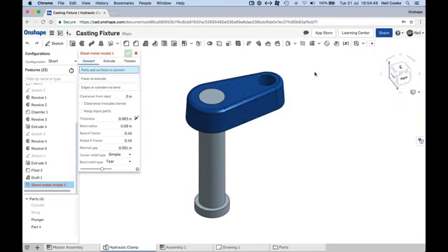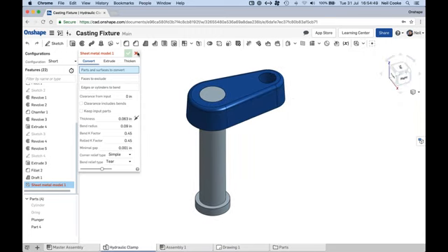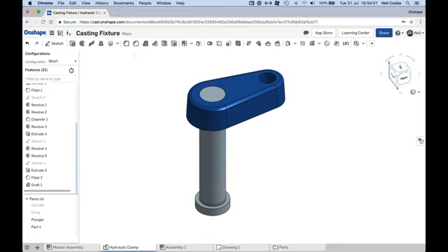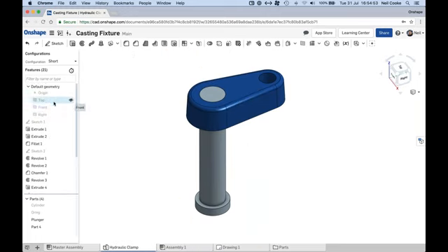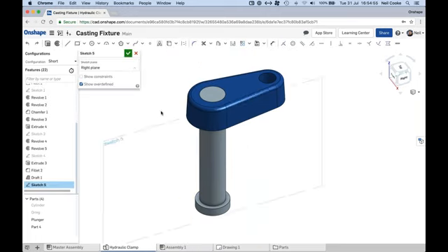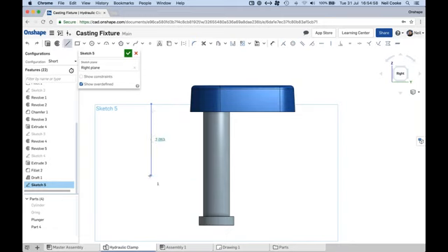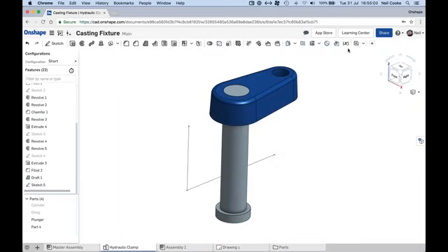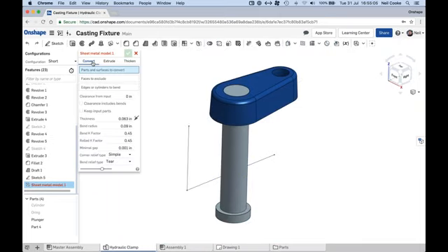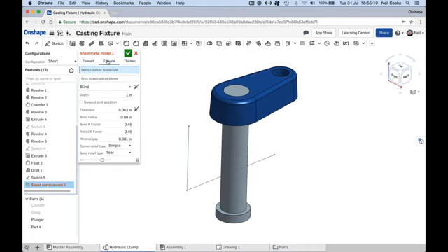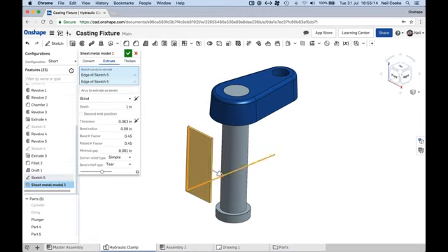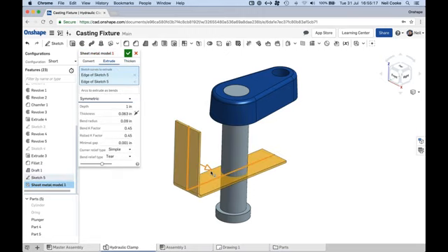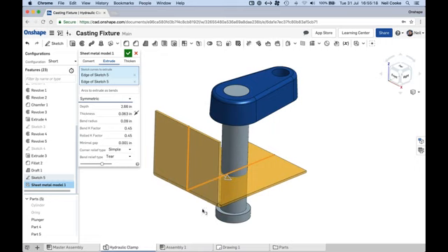The difference here, and let me just do a real quick example, I'll just sketch 2 lines, something simple like that. If you're doing sheet metal, then you have the option to convert a solid to sheet metal, very similar to the way you can in SolidWorks. You can extrude, you can thicken a surface, or you can extrude 2 edges. So likewise, you might want to make this thing symmetric and drag it. You can see it's already put the fillet in.